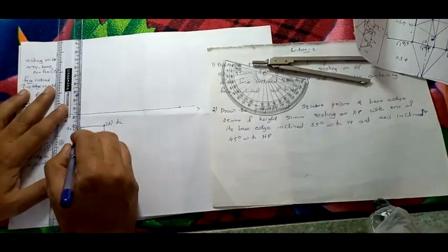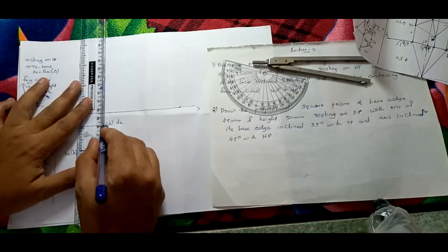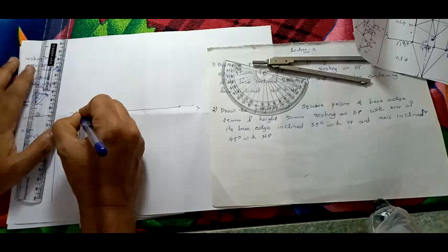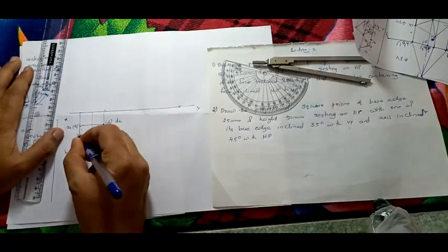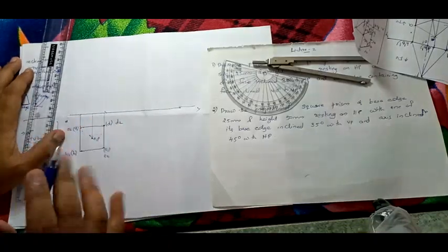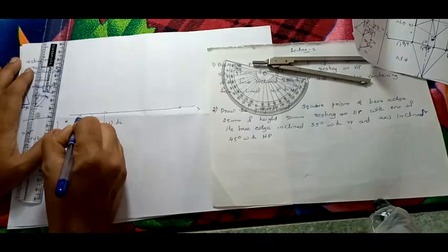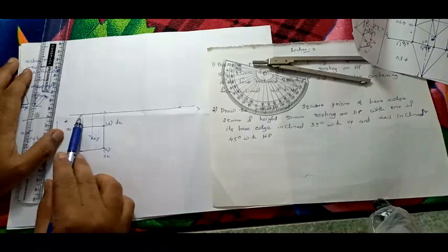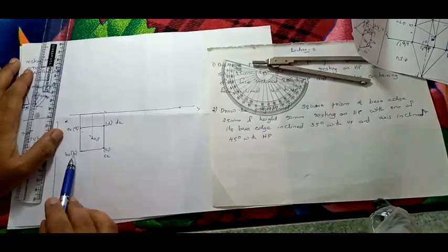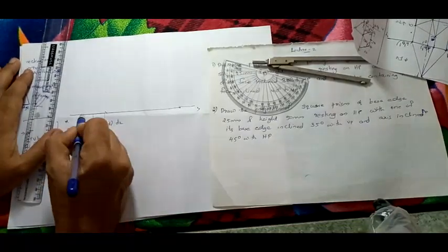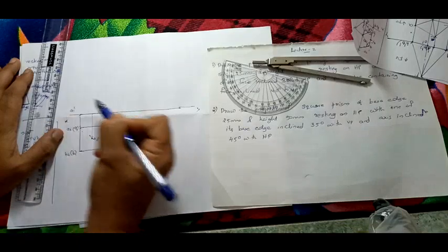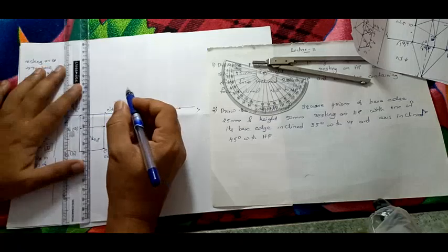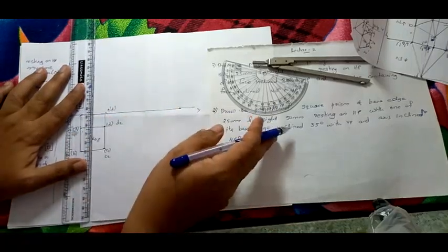So we will draw projection lines from here. Now from here also draw a line. We have to find the point, right? See carefully. Bottom means not visible, top will be visible, right? Bracket is your bottom. So this point is A1 dash, B1 dash, and this point is C1 dash, D1 dash. Now you have to mark the height. Height is given as 50 mm, right?